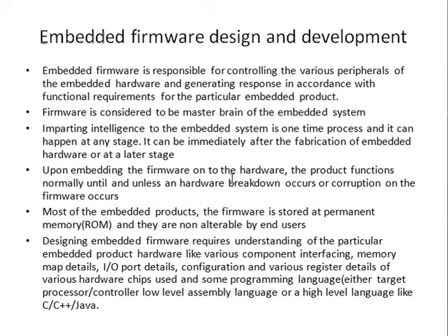Then you have that firmware is actually the piece of code which keeps on running an infinite number of times till there is a hardware breakdown. Only under hardware breakdown, if the device is completely hanged, will the firmware be stopped from running. In most embedded products, the firmware would be put onto the ROM. It will be stored in your ROM permanently, and at any cost it cannot be erased by any user. But there is a method to modify the firmware versions, which you can change with the help of operating systems, which we will probably discuss in a later class.